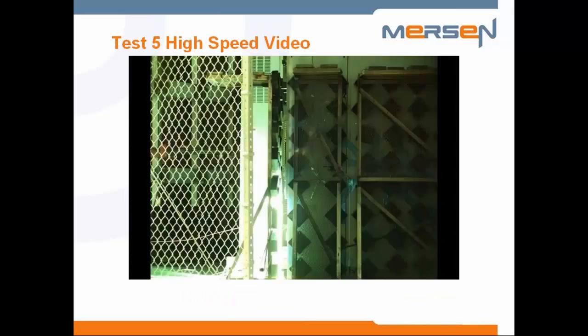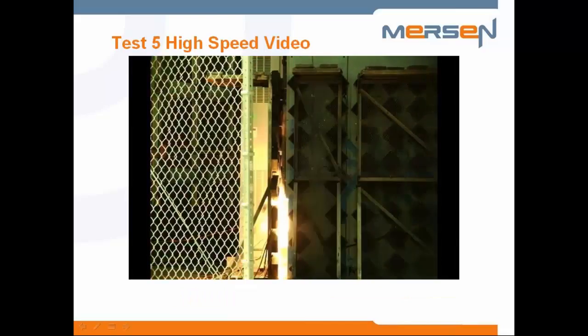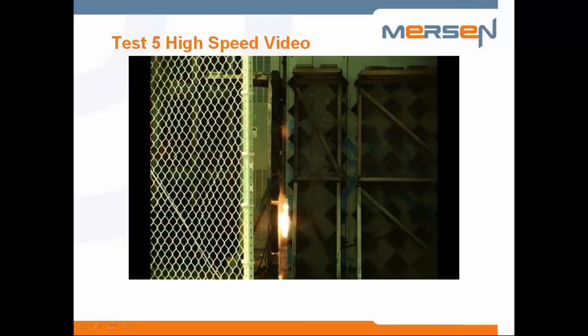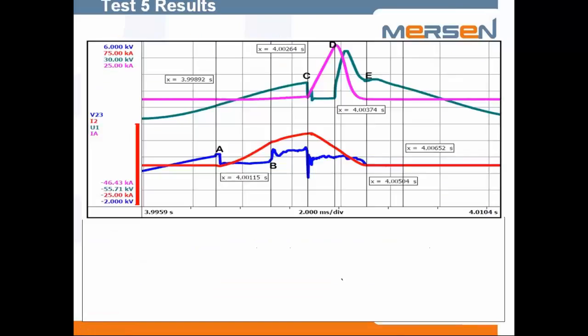This is with a high-speed grounding switch in place, and if you notice, before the gases can be ejected from the equipment, it has been extinguished. And so what we need to do is look at this a little bit closer to see how well this performed. What I'm showing you here is the traces from that last test where the high-speed grounding switch was called upon to open it. The total clearing time on this was less than a half a cycle.